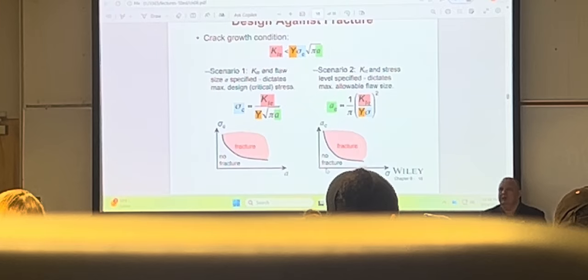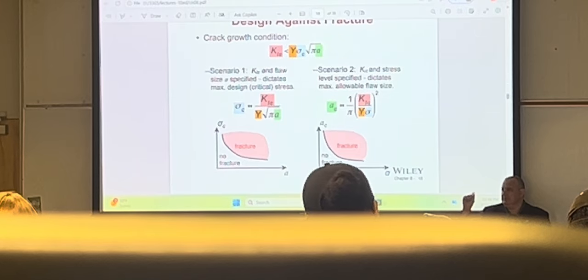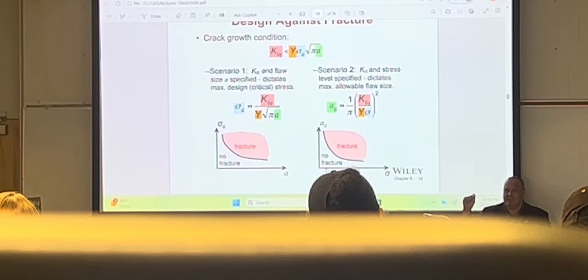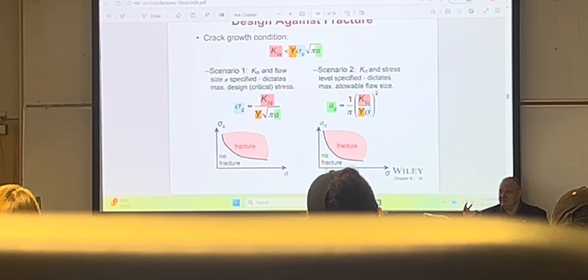And when I worked at Motorola, Motorola makes a power amplifier. It's a chip about 2 millimeters by 2 millimeters. It's gallium arsenide. Gallium arsenide wafer, 4 inches. I don't know how much it is, but it's like $1,000 for wafer versus $10 for silicon. But each cell phone that you have has a power amplifier, 6 transistors. There's 25 microns of gold on each side. Sometimes it goes kaput. And it's still amazing to me that back in the day, it was sold for $2 a piece. Can you imagine that's the scale of the economy? When you have a wafer, you can calculate how many pieces of chips you're going to have on that wafer.